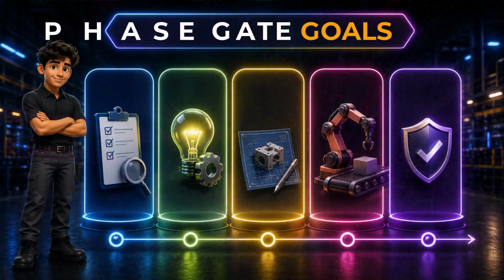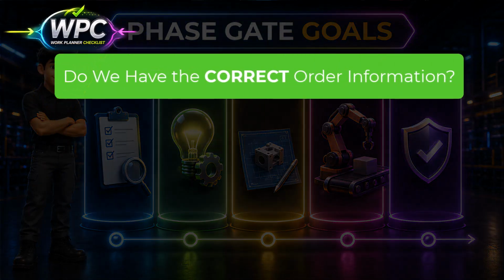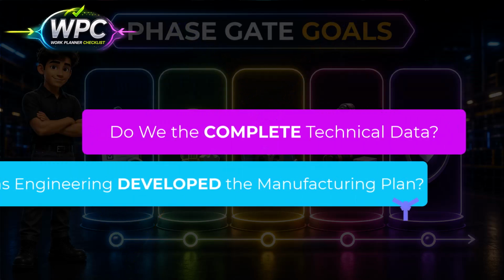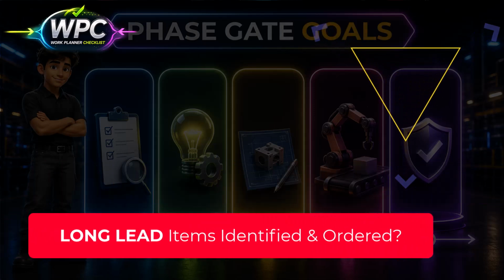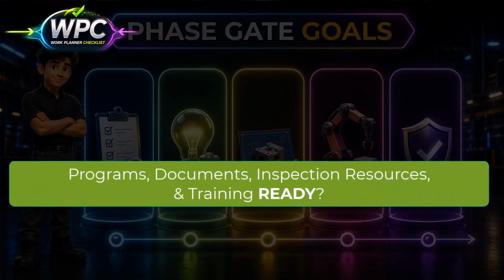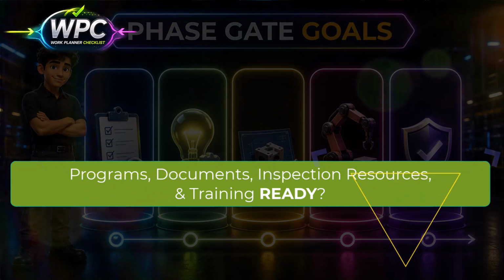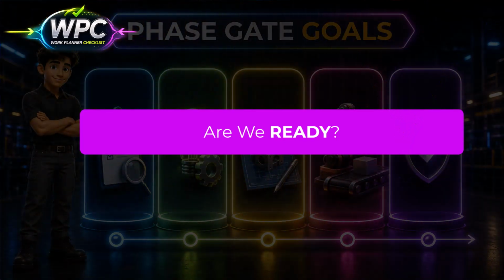Think of each phase as a readiness gate. Each gate asks, do we have the correct order information? Do we have the complete technical data? Has engineering developed the manufacturing plan? Have long lead material, tools, gauges, fixtures, and outside services been identified and ordered? Are the programs, documents, inspection resources, and training ready? And finally, are we truly ready to release the order to production?